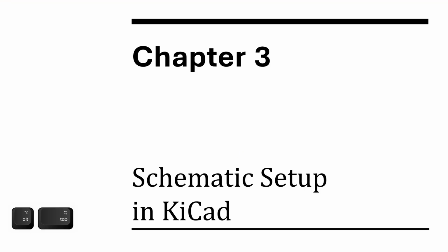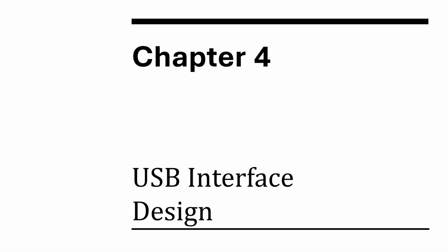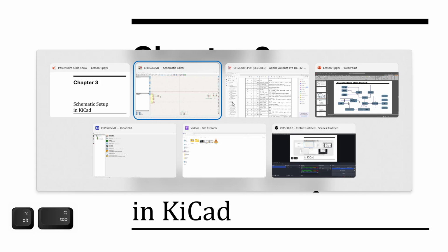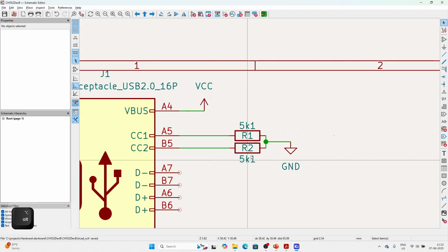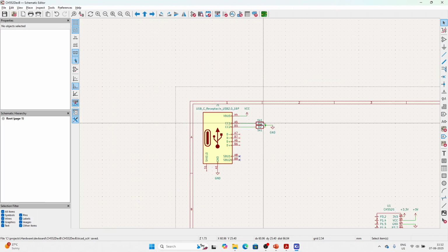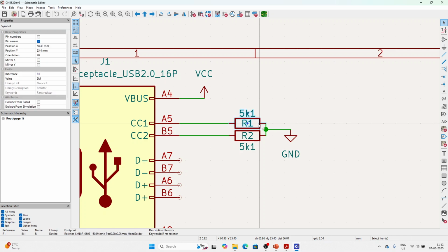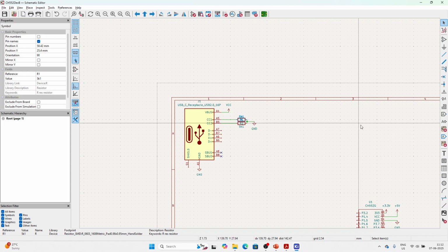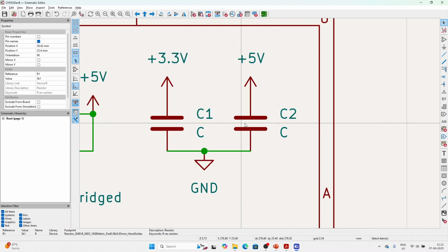So that's what we had talked about on the schematic. That would be the start of your schematic. How do we place components? How do we change the values? Here we learned about changing values by pressing V, which opens your edit value field. I have to edit a value here as well, 5 volts and this.